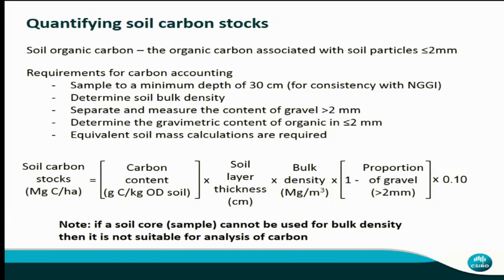So, given that, this challenge that everybody thinks about getting bulk density, if you do your sampling carefully, it should be fine. You need the mass of soil in a defined volume. And that's the key. Get your volume defined, take all the soil out of that volume. You need all of it for the carbon count too, to get the carbon measurement right.